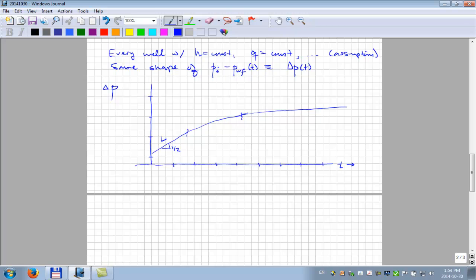And then out here, basically this delta P is going to be proportional with the natural log of time. That's describing what we call full radial flow. So you start getting flow regimes where you're seeing this radial flow going out. And this is what I'm going to call T for transition, not transient, but transition. Linear, transition, and radial.